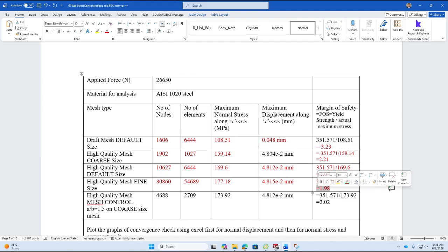Now, what I will show you next is a clever technique. Again, maybe in this small part, it's not very important to use that. But think about it from a practical point of view. You're doing a full chassis of a car, right? That will have so many holes like these in different places. You can't go on and mesh it with this kind of a mesh, right? Because it will crash your computer.